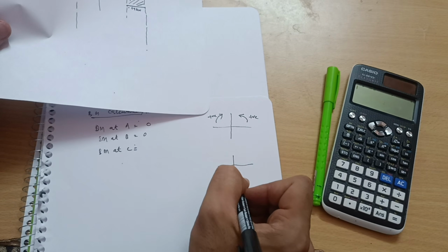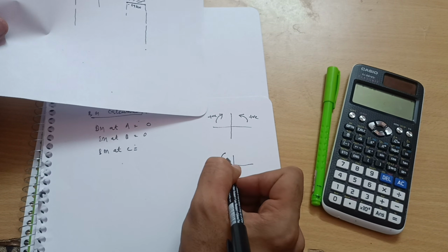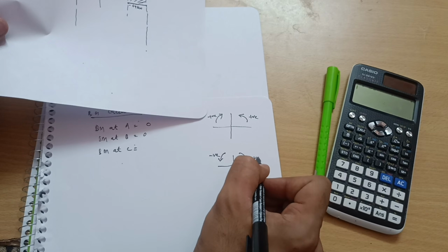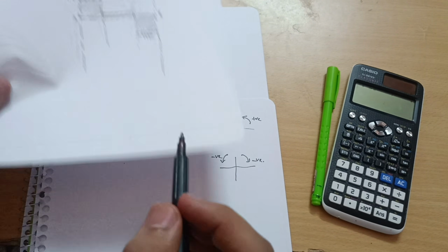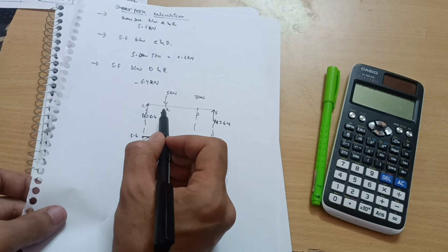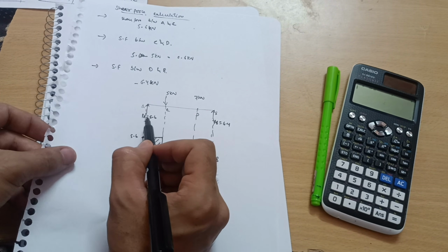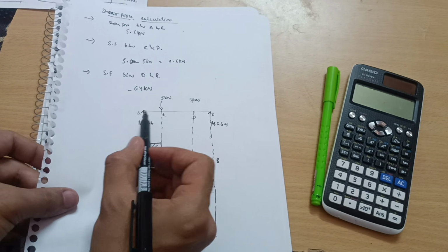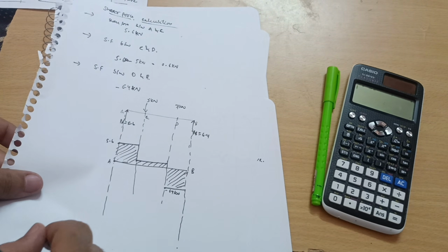Second case is, if this is the section, if the force is acting anti-clockwise on the left hand section, that is a negative value. If it is clockwise on the right hand of the section, you have to take that one as negative. Now see here, bending moment at C, the summation of moments I have to take on the left hand side or right hand side. So I can definitely go for the left hand side, as only one force is there, that is your RA. It is acting clockwise with respect to C. See here, this is your force which is acting clockwise. I hope you are getting it.